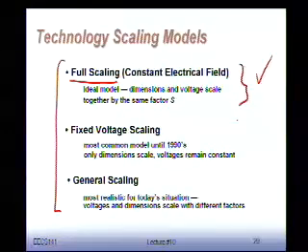Now, that's the ideal theory. Before that, however, before the 1990s, nobody cared about it. Actually, it turned out that the industry was perfectly happy with the same supply voltage. Say, well, why don't we? They fixed the supply voltage at 5 volt. It was a good number. TTL was 5 volt. So why not stick to 5 volt? It's a good round number. We have all our supplies sitting at 5 volt. The boards are designed, the interfaces are designed at 5 volts. So they stuck to 5 volts forever.